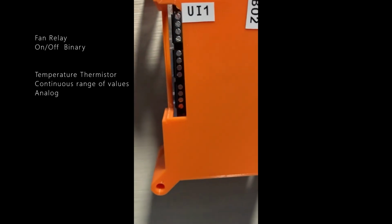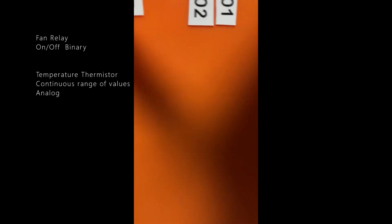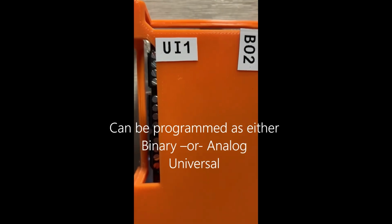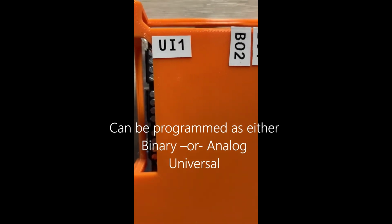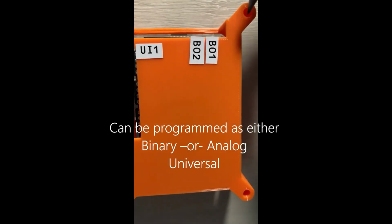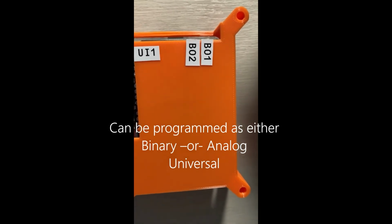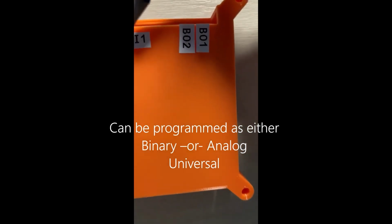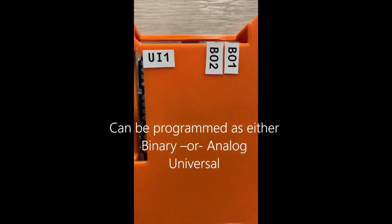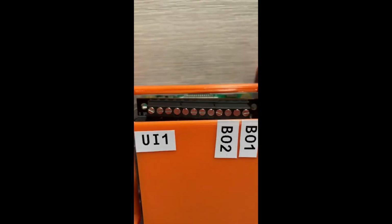The thermistor, temperature input, provides a continuous input of ohms and is wired to what is labeled UI1 over here. You may wonder why the temperature input terminals are labeled UI. That is because BAS controllers like this one may allow the user to configure the input or the output to be either binary or analog. The type of terminal that can be programmed as either binary or analog is called a universal input or output. Overall, you will notice that we do not use the full input and output potential of this controller.